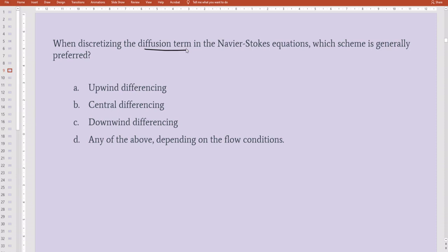That is mu into del square u by del x square plus del square u by del y square plus del square u by del z square. Yes, that is our mu del square u, this term on the RHS actually. So the diffusion, the term diffusion itself says that something of a second order. So that is dou square u by dou x square plus, like, second order terms are involved, so normally these terms we have been calling as